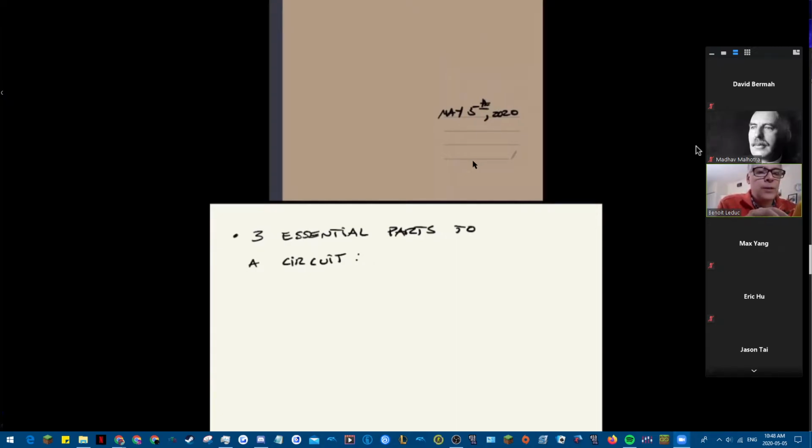And V is the volt. So I'm going to set it at 20 so it can record up to 20. I have two terminals right here. This is called the red terminal. This is called the black terminal. And whenever I put this across two points, I'll do it right here.